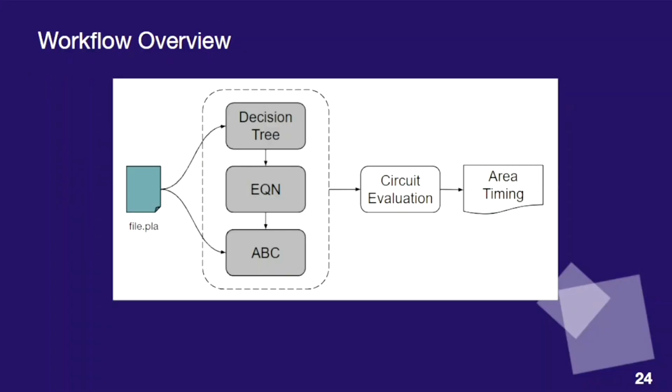But to be sure that this decision tree is a good alternative, we decided to compare other methods with it. So this workflow presents the methods that were compared with the decision tree approach and will be presented next. We call these three methods direct Verilog, which shows the simplest and most direct way to obtain the synthesis result, ABC optimization script, which goes through an optimization process in the traditional ABC logic synthesis tool, and the decision tree training for logic synthesis flow, which is the focus of this work and intends to achieve the goals mentioned previously.